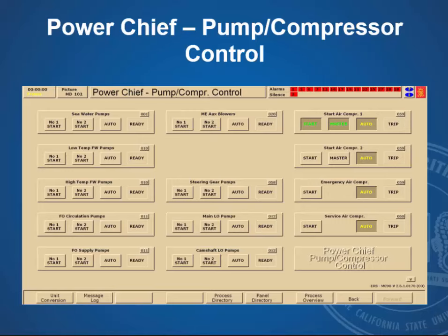When you got down there, both of these pumps would be running. So hopefully you know which pump was on the line before the casualty. You would shut that down, see if your pressure's okay, everything's copacetic, then try to put it back on the line and try to determine what the problem is.